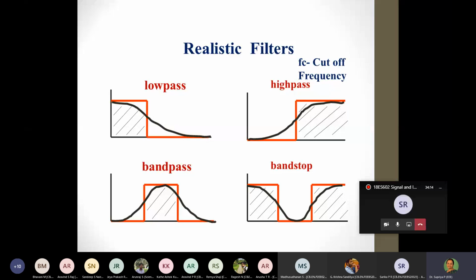Many qualities are attached to the filter, but basically it means it is not going to just cut off the frequency at 50 hertz. Even before it, it starts slight attenuation, and it does not cut at 50 hertz. It allows some frequencies beyond 50 hertz also, as can be seen from this graph. You will see that there is a drastic change in the actual response.